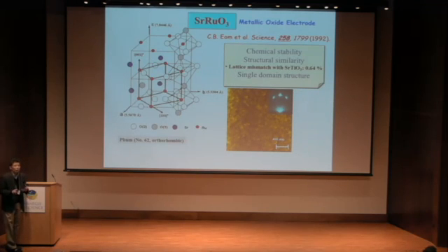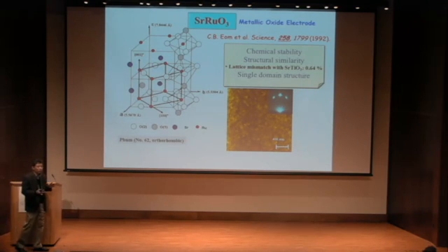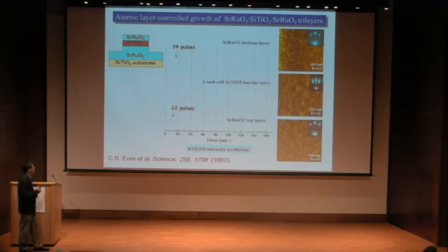In order to do this test of the bottom electrode, we need a single crystal metallic oxide electrode which has the same crystal structure and almost the same lattice parameter, for coherent growth. We use strontium ruthenate, which is a very good metallic oxide, screening perfectly well. Then you grow strontium ruthenate, strontium titanate heterostructures. You can see beautiful step structures, and you can count the number of unit cells. For example, this is a 6 unit cell barrier, and the top and bottom electrodes can be maintained.